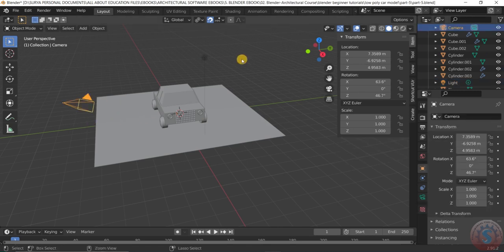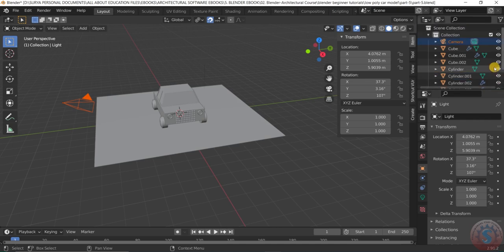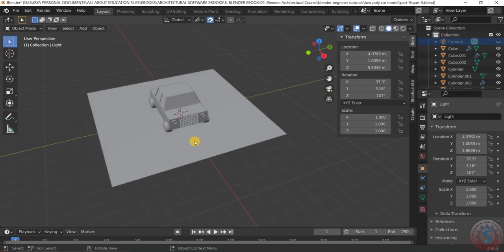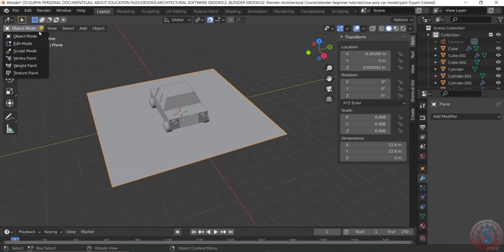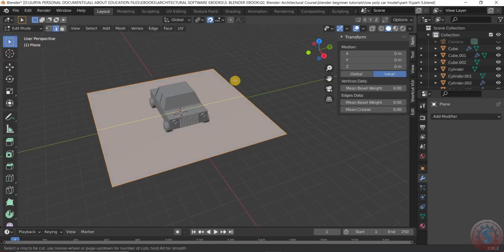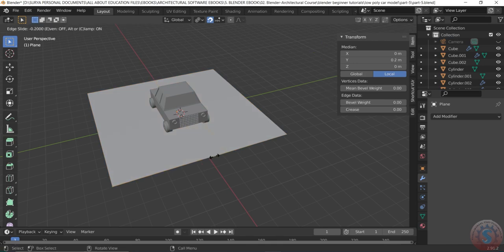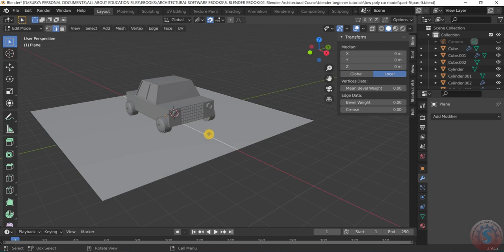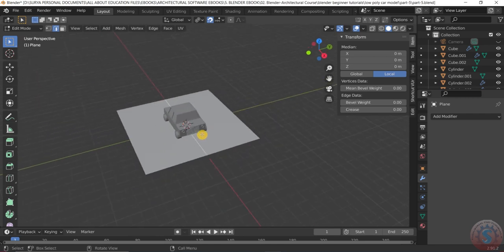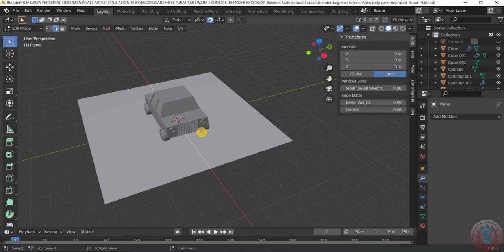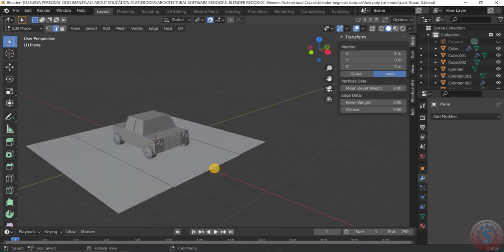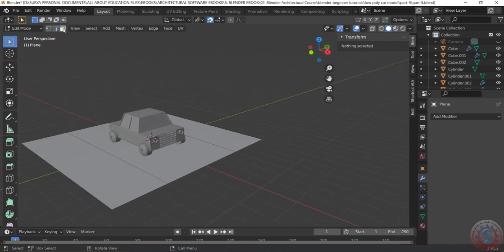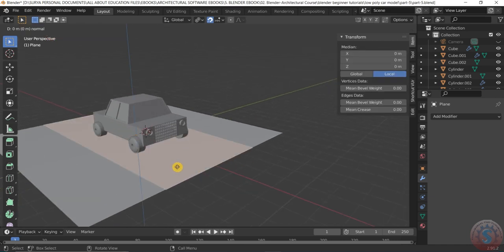Then after I want to create the hide this again, it is disturbing, and select this and hide the light and camera, and again give the plane by using the edit mode, Control R, give the loop cut because on the left key it is there. Again select the loop and give the Control B to bevel this somewhat distance, and give the face and extrude this somewhat.